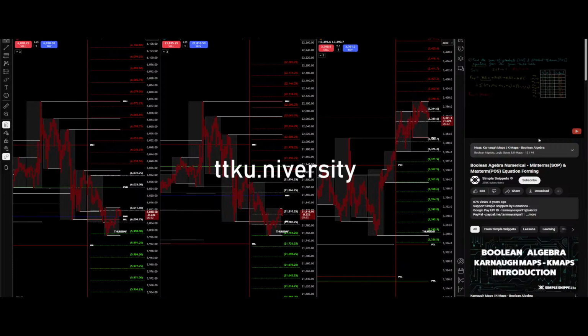So let's look at this case. In order to get output as 0, we need to take complement of B as well as C. And since it is a product of sums, we have the sum term over here, we have the second sum term and we have a product sign in between, and it would be A or B complement or C complement. For the third sum term we have A complement or B or C complement, and for the last term we have A complement or B complement or C complement.